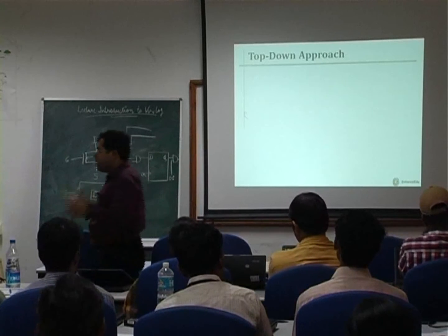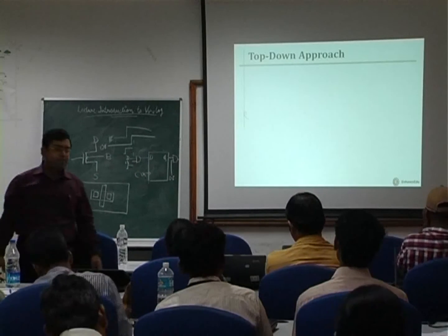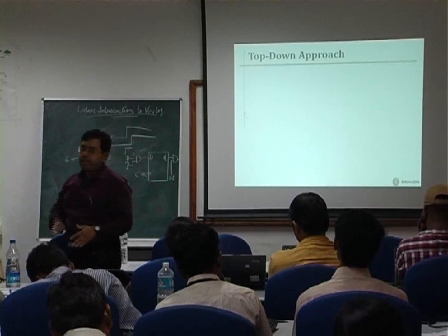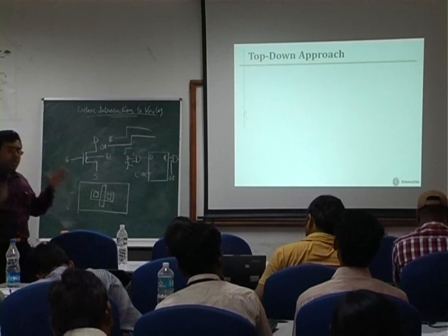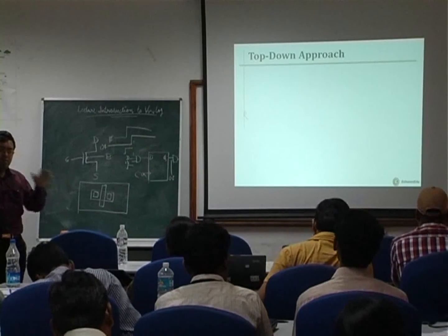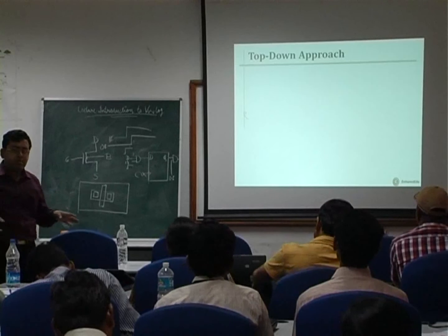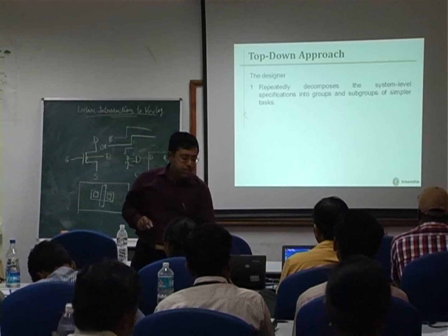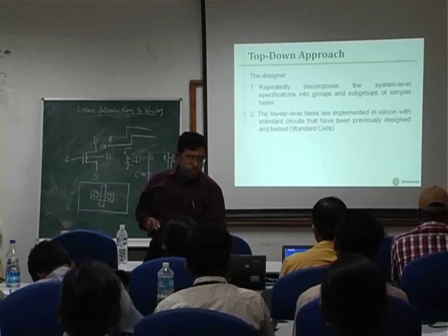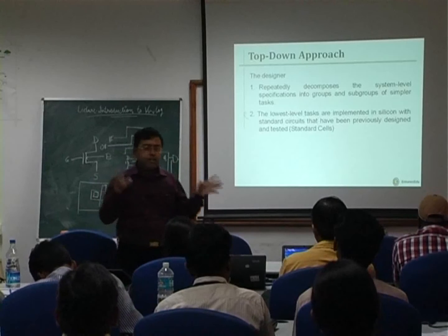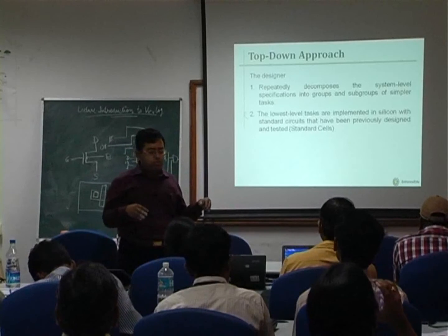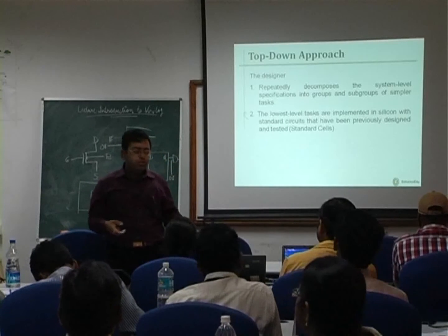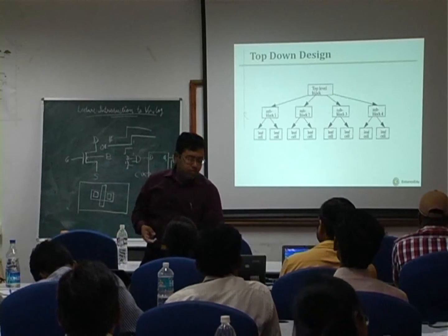So what are the approaches by which we can model the hardware? Two popular schools of thought are there. One is that you start with the whole design, split it into modules and submodules, ultimately arriving at the elementary level modules. That is what we mean by the top down approach. Once you arrive at the elementary level modules, you implement them and then integrate those modules together into a solution for the whole.